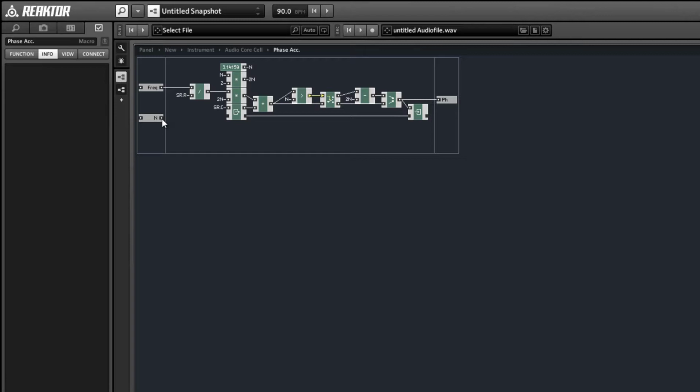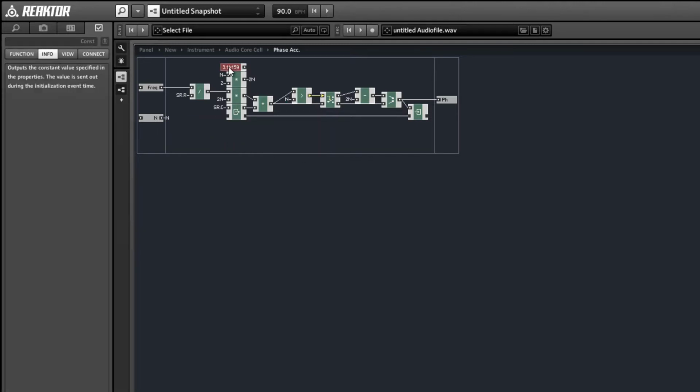So I'll just create a new input, name it n, and then connect it to the quick bus n. And you'll note that when we do that, the old n value disappears. And that's because you can only have one value supplying that quick bus at any given point in time. So we can delete the pi value that we had previously declared.